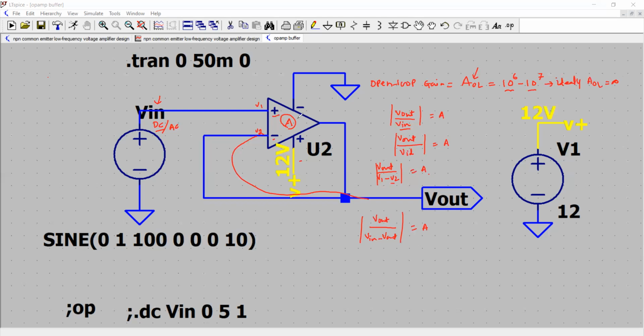The function of the op amp is that it is a difference amplifier. So it will amplify the difference between V1 and V2 and nothing else. It doesn't amplify the individual signal, rather it amplifies the difference. And that is how we say that V out is equal to A times VID.